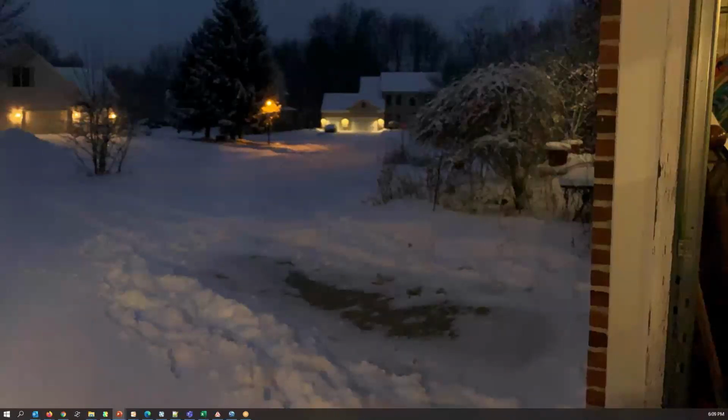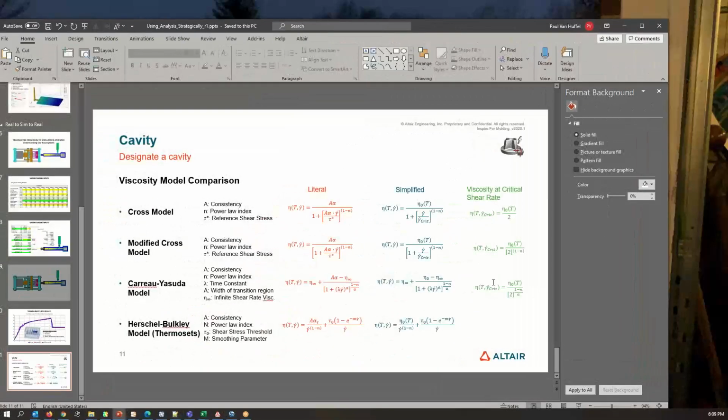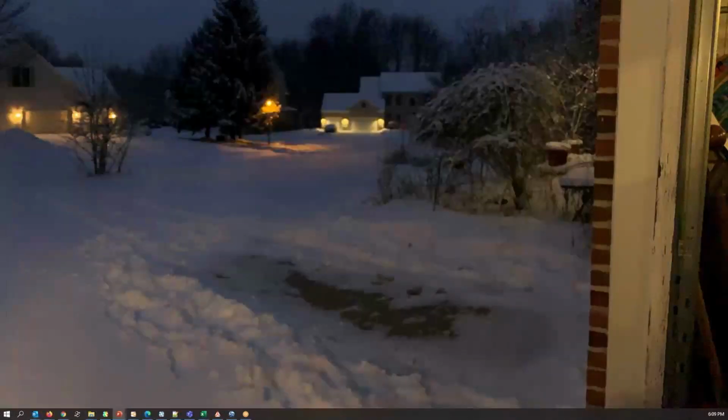And so pressure dependence factors into that zero shear rate viscosity. So when you're looking at η0, that's our zero shear rate viscosity, and that's the thing that will be affected by both temperature and pressure if we do both temperature and pressure dependent. Temperature dependence is accounted for with the Williams-Landel-Ferry equation for time temperature superposition. That does include a version that has the pressure dependence, and that's what I was doing in that other example. That's part of what I was testing there.